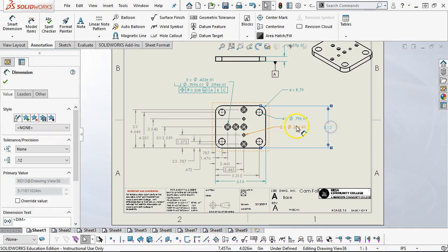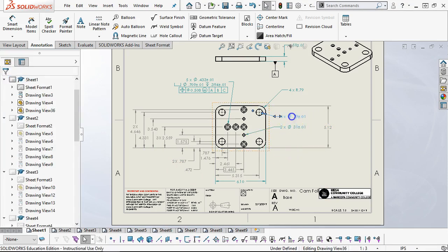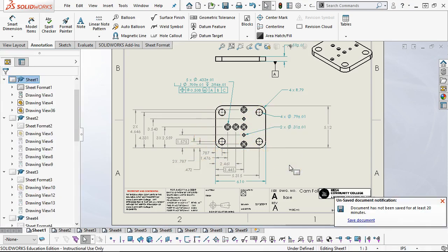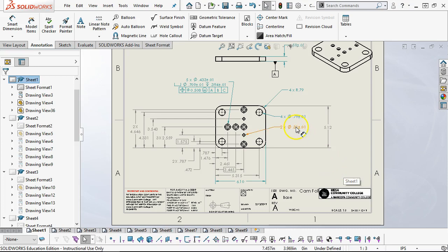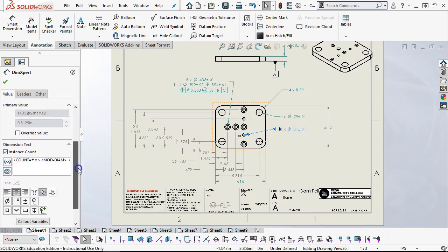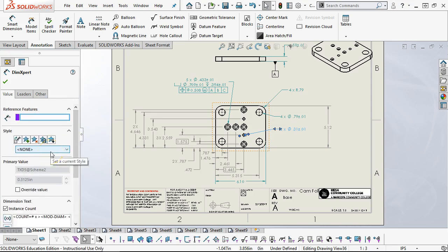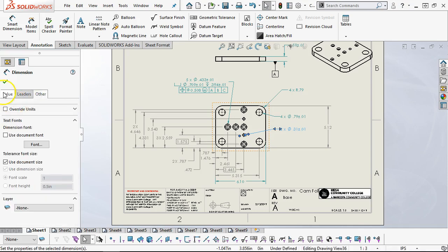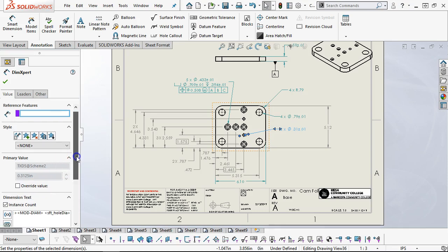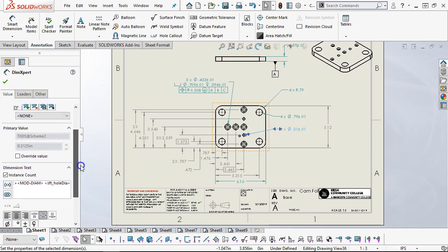All right, so your task is to think about the positional tolerances for each of the hole locations. Now that we've established those positions, let me go ahead and save the document. Do they need to be 2 decimal places, or in the case of the pins, if we actually bring this over to, let's see, that picked up. All right, so since this picks up from the dim expert, the values, the style, the tolerances aren't accessible.